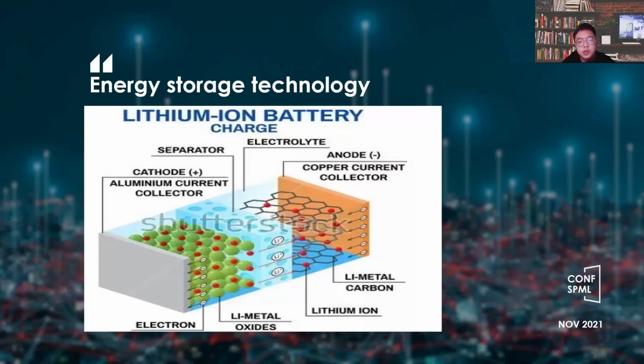However, because the voltage or capacity of the single battery cannot meet the use, it needs to be combined in series and parallel to satisfy the conditions. In addition, because the internal resistance and capacity of each battery are different, the performance difference may lead to the reduction of the available capacity of the battery pack, thus shortening the service life. Consequently, it's necessary to use battery equalization technology to protect the battery pack.